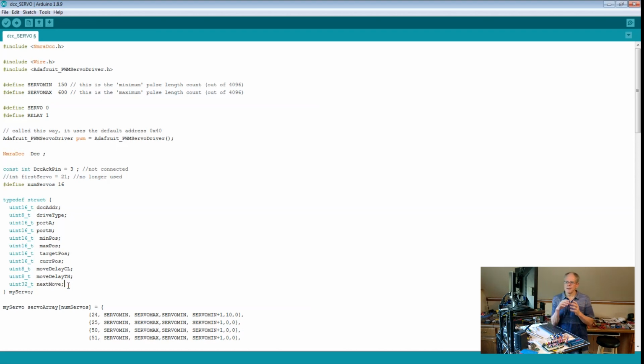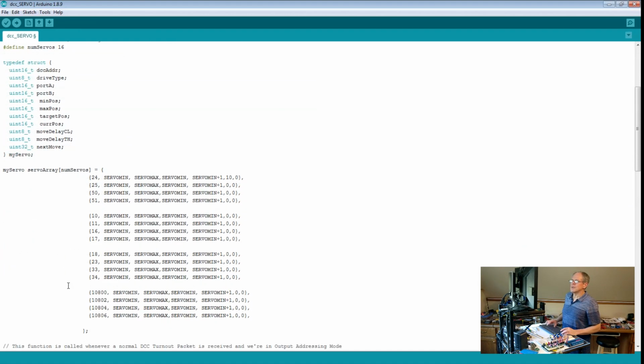The reason is last move, as you remember, I was setting that last move variable at the time when I did an activity in moving the servo, and then I compared that last move time, added to the last move time my delay time, and compared that to the current time, and if current time was actually greater than this addition, I took the next action. Now that means every time I'm going through there I have to make that addition. So I'm changing that around. I make that addition just once at the time when I calculate the next time, and then I have to compare the current time only to one variable without additional computation. So that makes the code execute faster, and we are looking for speed, of course, all the time. So that's it. Now let's look into what that means.